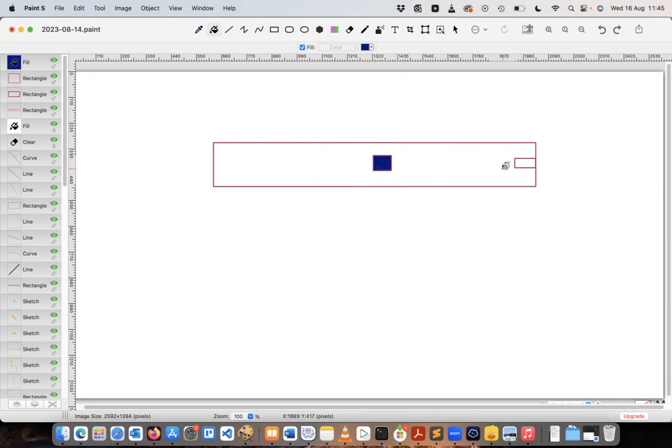And on this end, we are concerned with how long it takes for the petroleum to reach a certain level here. And we are also interested in how long before the concentration here drops to a certain level. All right, so take a minute and write the balance for this. So just for the sake of practice, develop the unsteady state material balance that describes this situation.